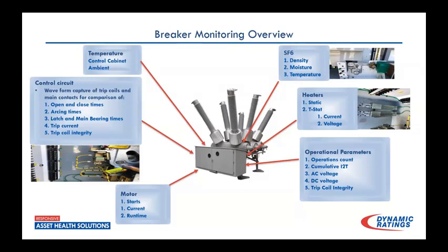I recommend it, it's something I implemented at a utility, and something I recommend to all of our customers. Really, you have to institute some maintenance tripping of these breakers. You'll have breakers that'll sit there for 10 years and they don't move. And that's really the biggest enemy to these breakers operating when you need them to.